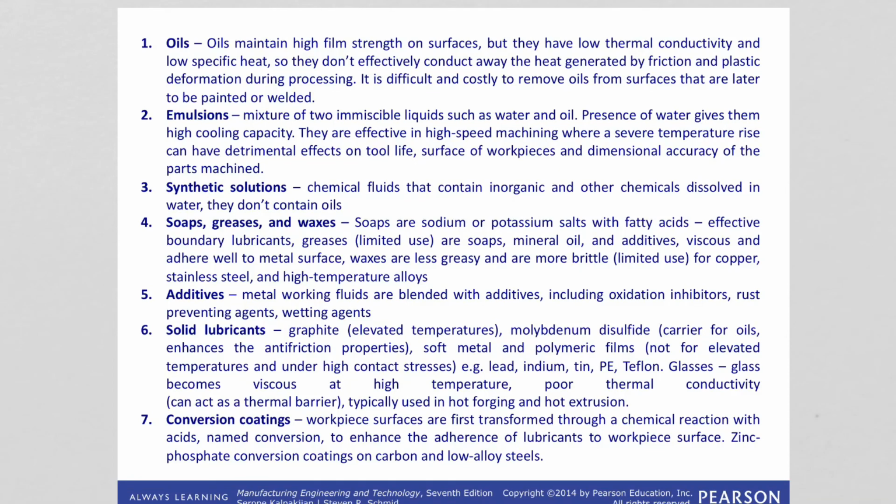Additives. So many times metalworking fluids are usually blended with additives, including oxidation inhibitors, rust preventing agents, wetting agents, or antiseptics. So sulfur, chlorine, phosphorus, these are important additives to oils.